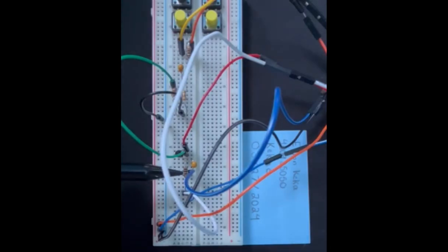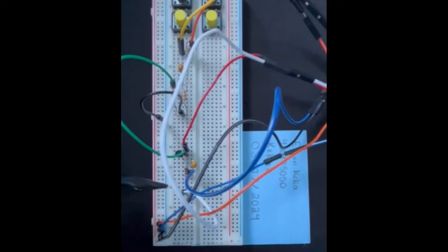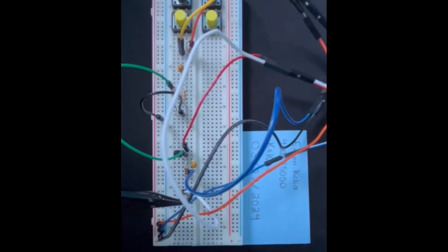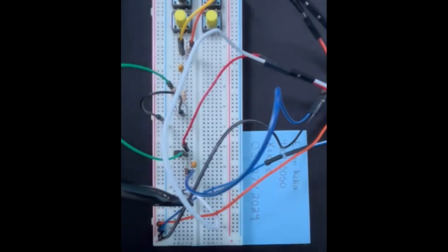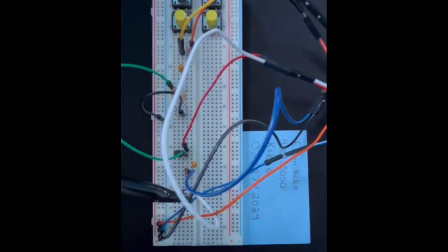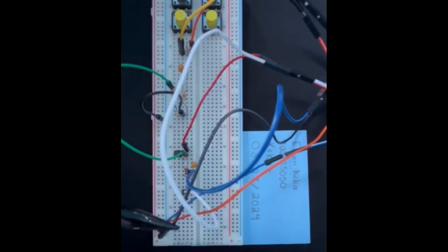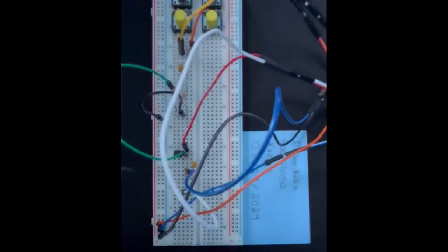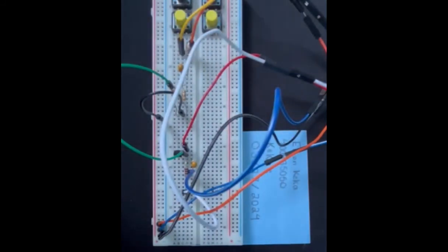The 100 ohm resistor is then connected to this white wire, which is connected to the negative 5 volt input. Then we have this blue wire here, which is the negative terminal of channel 2, which is simply connected to ground. This orange one likewise is negative channel 1, and then this black wire is simply the ground connected to the 82.